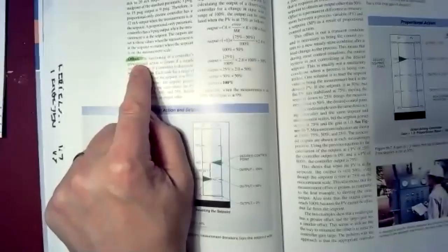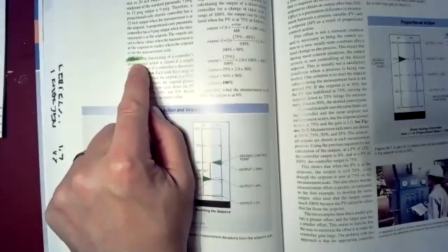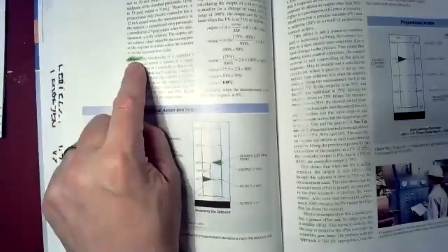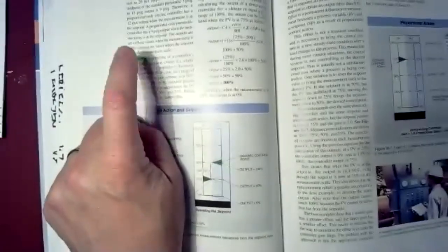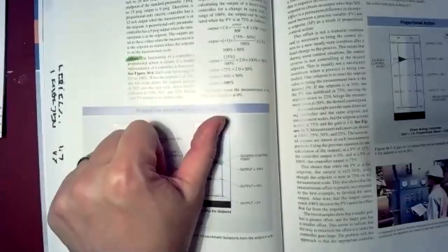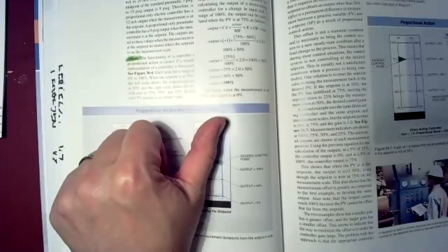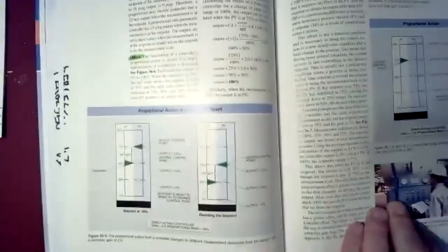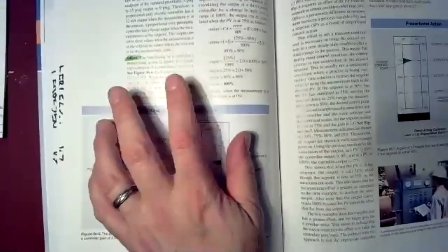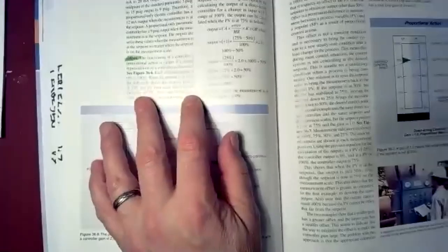Sometimes I have a minimum valve opening I want to always maintain. So that minimum distance, like percent open of that valve, might be an offset of 10%. So I always want to maintain on my output a certain offset. It can also be related to the process variable. So offset might be a number that you set as a parameter in your controller. If you always want to have it running 50% open minimum, you might set an offset of 50%.